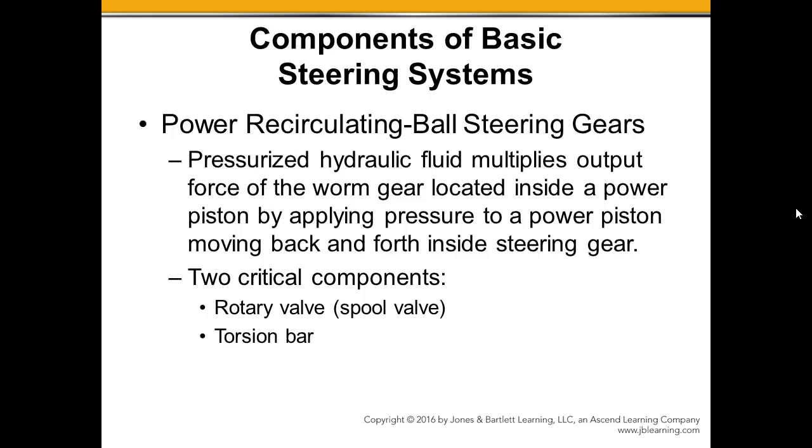The main part of the power steering unit here, we need to make sure that we understand that the steering gear or the steering system is a manual steering system with power assist. That way, if we have a failure in our power steering system, it still reverts back to manual steering.